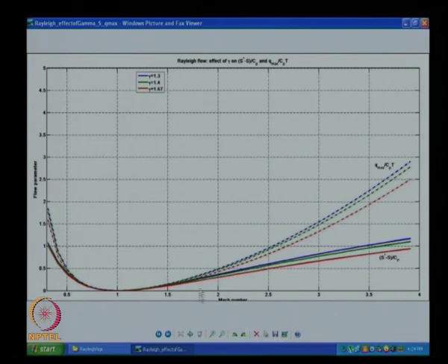When in supersonic condition, that is not the case. S is almost equal to S star already compared to the subsonic situation. That is the way. The entropy change in the subsonic case is higher than in the supersonic case. Of course, the subsonic case only goes from 1 to 0, while the supersonic case goes from 1 to infinity all the way. Maybe that is why the curve is looking squeezed. We won't worry about that anymore here.